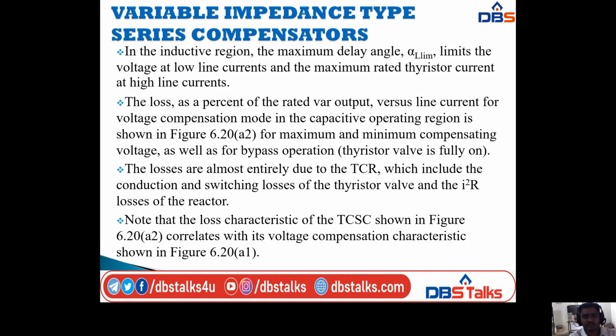Next, in the inductive region, after we discussed the capacitive region, the maximum delay angle, that is alpha limited, limits the voltage at low line currents and the maximum rated reactor current at high line currents.